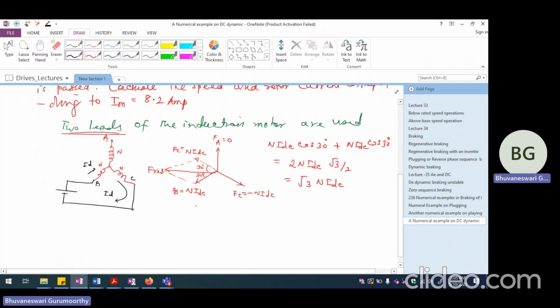And if I want to calculate the equivalent AC current, in the lecture class itself, we said that if I'm going to have a per phase current of IS RMS value, multiplied by root 2, which is the peak value, 3 by 2 times that multiplied with the number of turns per phase, this is going to be the peak value of the resultant MMF or revolving magnetic field.